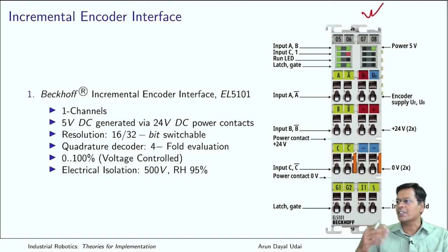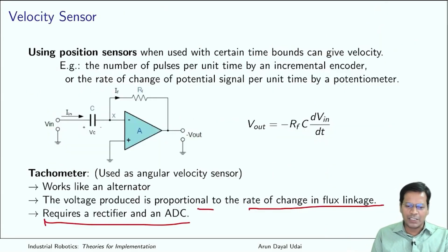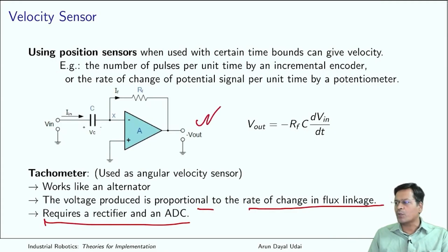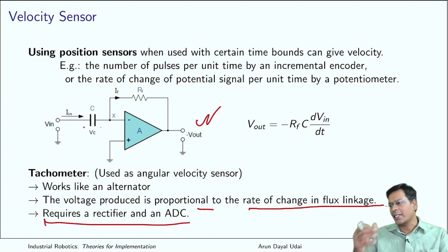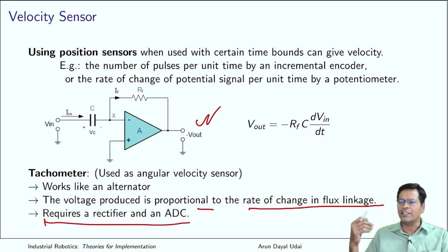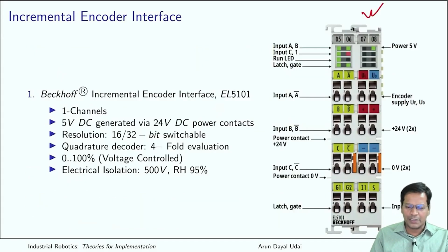In industry you need reliability which is at its peak, so there are a few methods of doing it. Maybe if I am able to acquire this voltage signal, in my own software I can take the derivative also. I can differentiate things in software. You can also directly take in the pulses from your standard digital input channel, and just count the number of pulses, and you will get the velocity. These are a few ways, but yes, in industry there are dedicated ways of doing it.